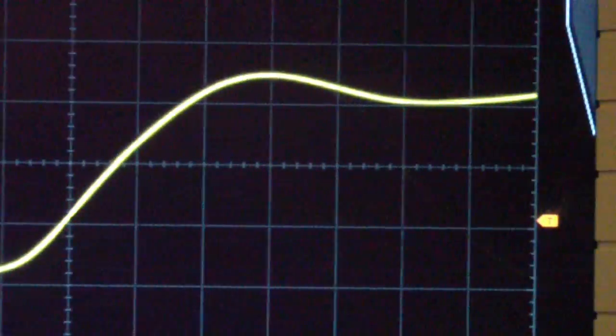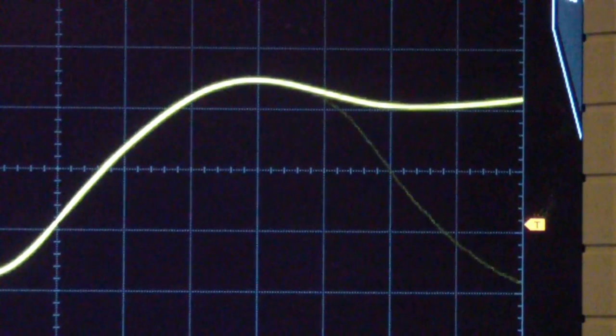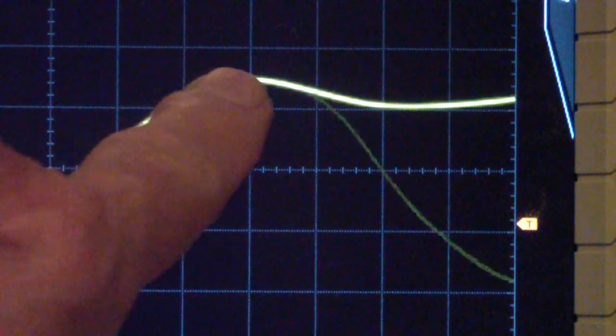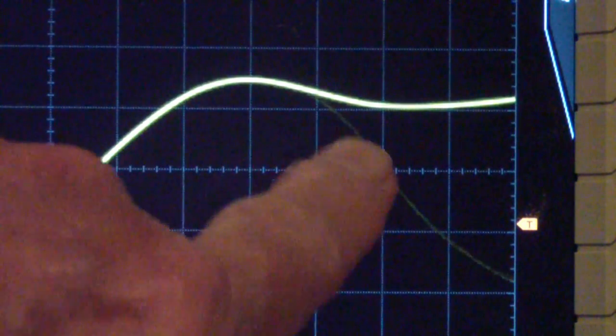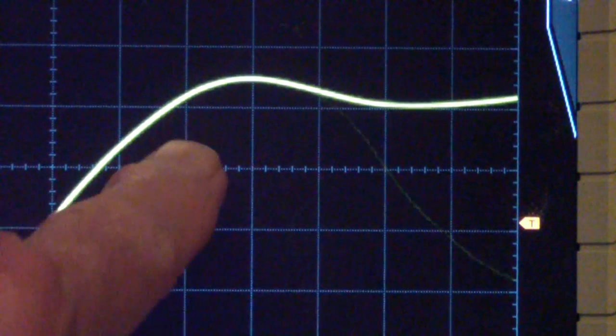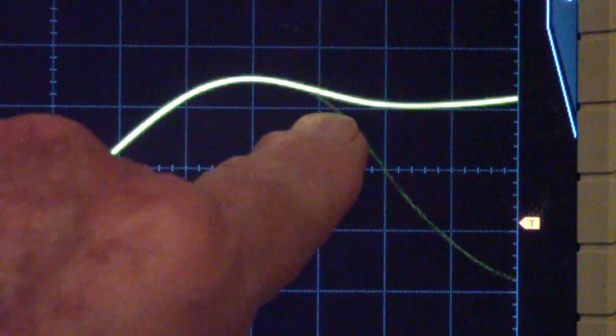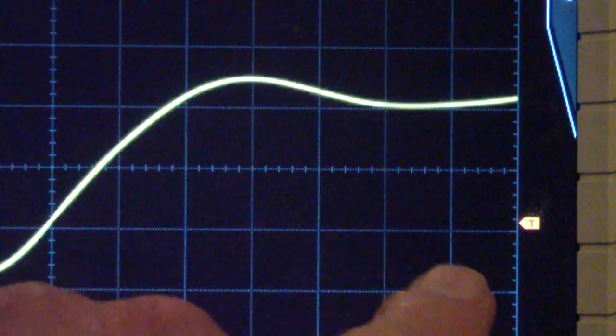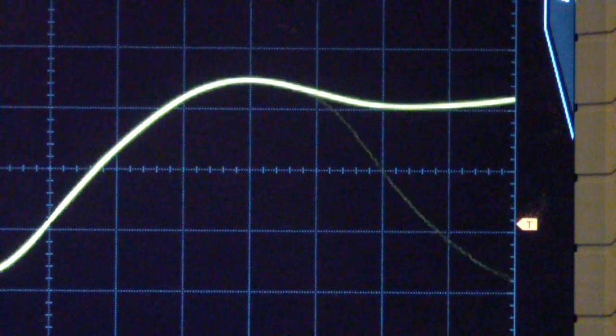You see the occasional short pulse. In other words, instead of rising and staying at the proper level, occasionally it mistriggers. Now, by mistrigger, the scope is not mistriggering, the signal is falling. It rises, and about 2 nanoseconds later it falls again. So this is a very tricky signal generally to work with. So let's see how the Digital Discovery handles it.